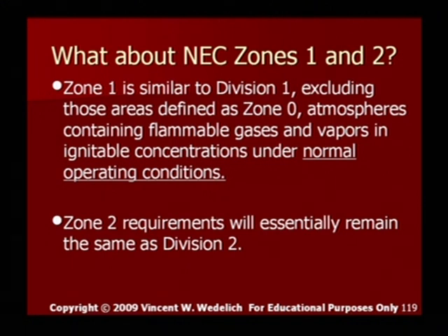So does that mean that if I have a piece of equipment rated for Div 2, can I install it in a Zone 2 area? The answer is no. You can only install a Zone 2 rated device in a Div 2 area. You cannot install a Div 2 device in a Zone 2 area. I don't understand that one, but that's the way the code's written.